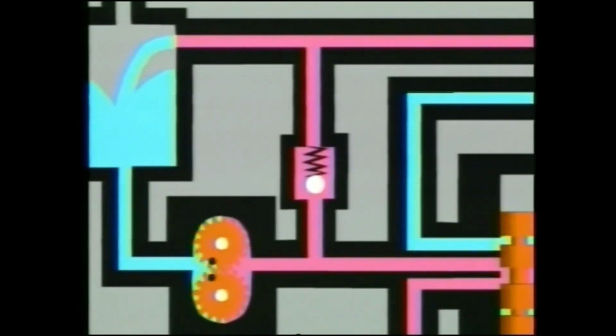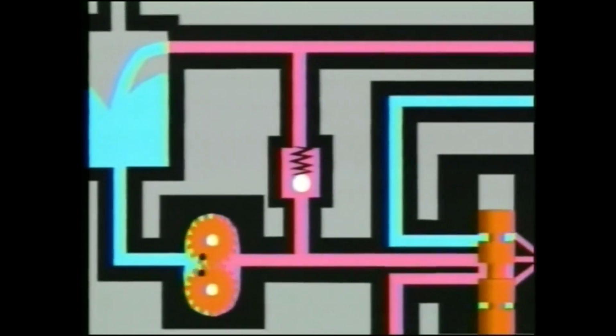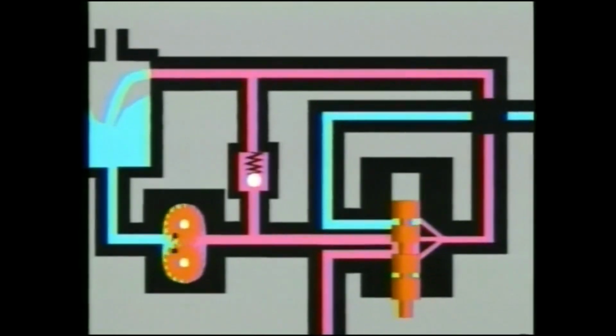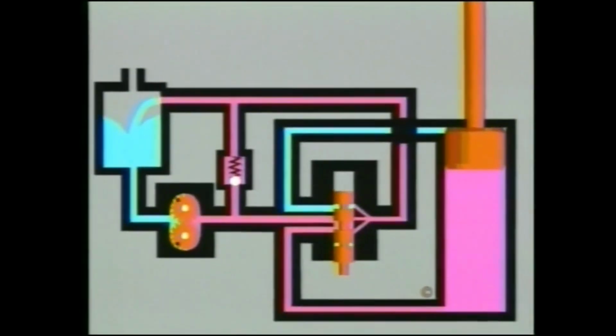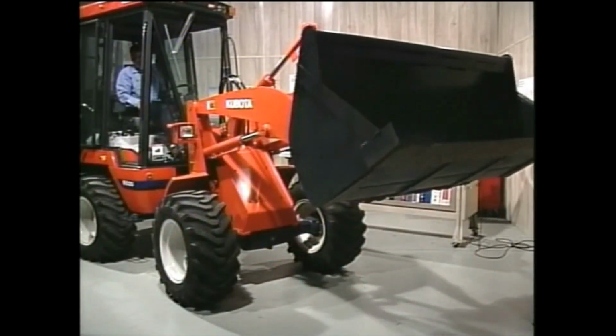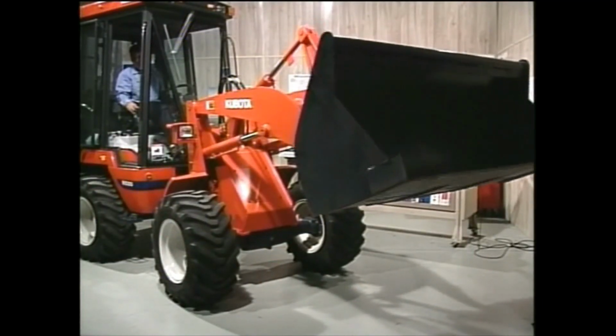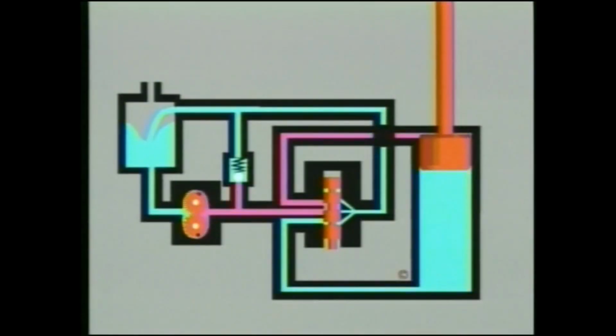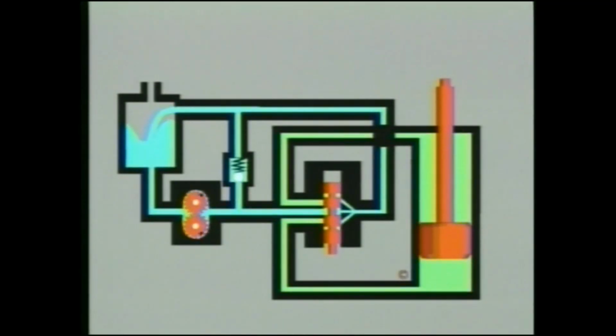Relief valves are installed in hydraulic systems to protect the system components from damage caused by excessive pressure. Relief valves limit system pressure by directing pump flow back to the reservoir. To reverse the cylinder direction of travel, the valve spool is moved to the opposite end of its stroke. The piston will stop when the spool is returned to the center position because the cylinder ports are blocked, hydraulically locking the piston.